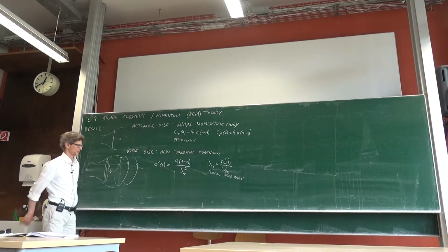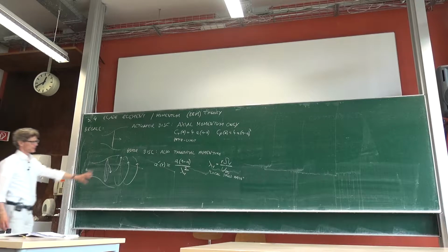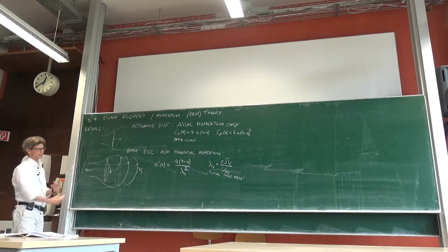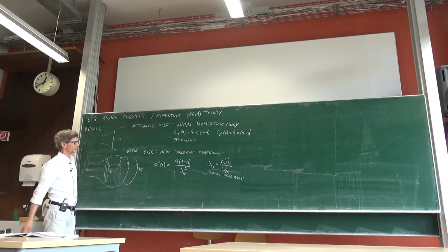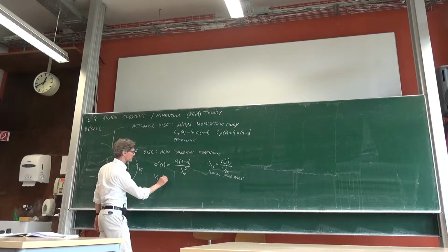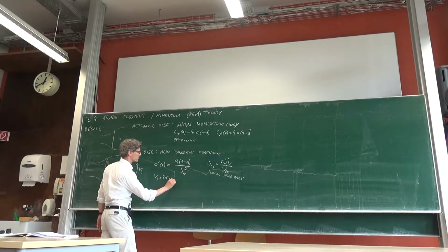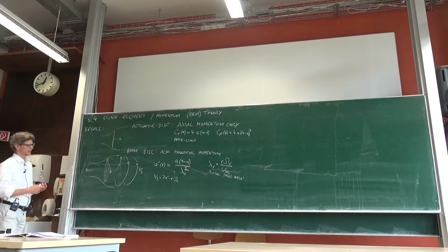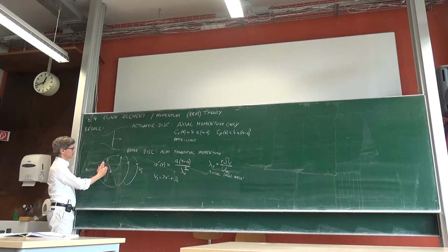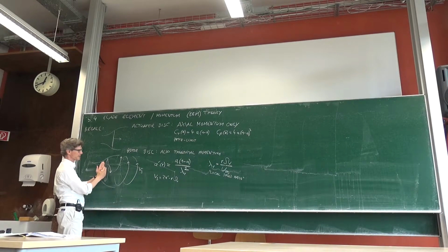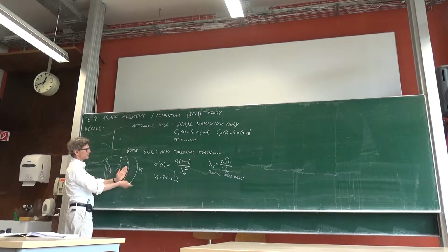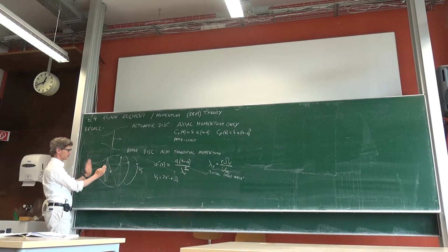So we assumed there was no energy lost. So maybe I should also say what was the velocity here that we called V3, the one that the air actually has, the rotational velocity, but as a velocity, not as a rotation velocity. Then V3 will be 2 times this induction factor times r times omega. So why 2? Because the assumption is, again, that there is rotation motion at the disk plane, which is just described by the induction factor, and then behind it, it's double. So again, at the actuator disk, we have the average of what is before and what is after.